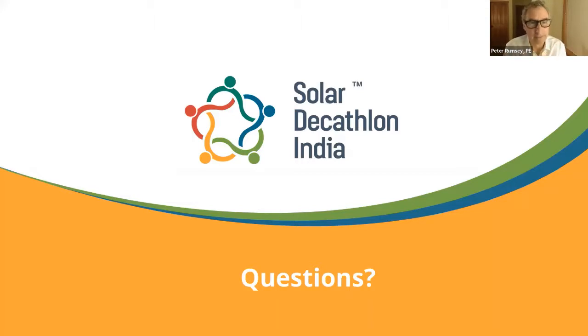That's one example. The question is on load calculations: how do you size these things? Well, what I would do is size each system for the job it's being designed for. In this example, we've got the compressor-based system for dehumidifying. We'd find the most humid day of the year and size the system for that. For the evaporative system, we'd look not at the most humid day, but the hot, dry day, and size for that. Then it's a question of which one is used on which day.